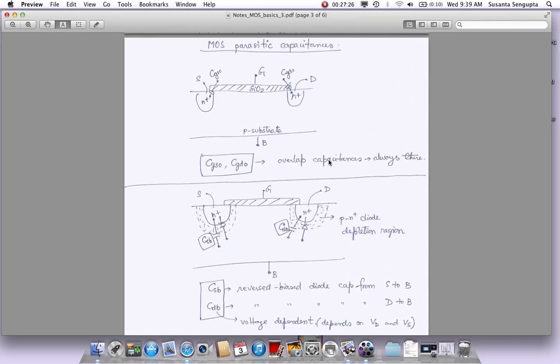And what it does at the end is, if you hear about all these different processes, in the olden days whatever the technology, 0.35 micron, 0.25 micron, 0.18 micron, they will further categorize by an FT. FT is a measure of the speed of the process. What that really meant was that you have a device with certain parasitic capacitances, and because of which there is only a maximum speed of operation you can achieve.